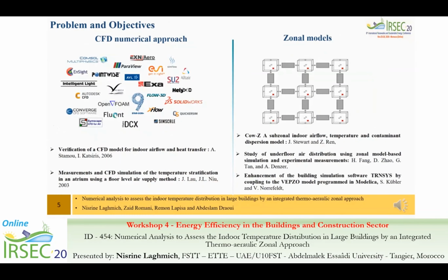In order to accurately calculate stratified air conditioning load, it is particularly important to predict indoor thermal environments. This can be predicted by two approaches: CFD, a numerical approach, and zonal models. However, the application of CFD models remains limited in the engineering domain because of its computational time. The zonal model is considered an intermediate approach between single zone and CFD models because the zonal method requires fewer zone divisions than the CFD approach and provides sufficiently detailed results.